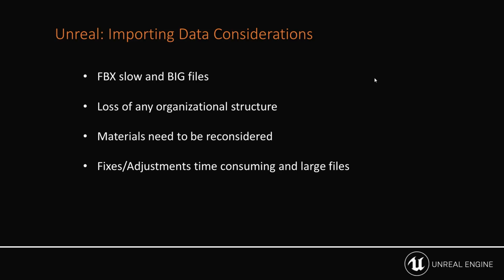So if I need to fix something that doesn't look right in Unreal, say for example with UVs, it can be time-consuming, where I may have to re-export the entire file to bring it back over to Unreal if I'm relying on something like FBX, depending on what that CAD data is. So I could risk loss of potential data of components if I'm moving back and forth with this. So we do want something that's going to be able to keep better control on that, and you definitely want to keep that in consideration if you're relying on something like FBX as your data translator.